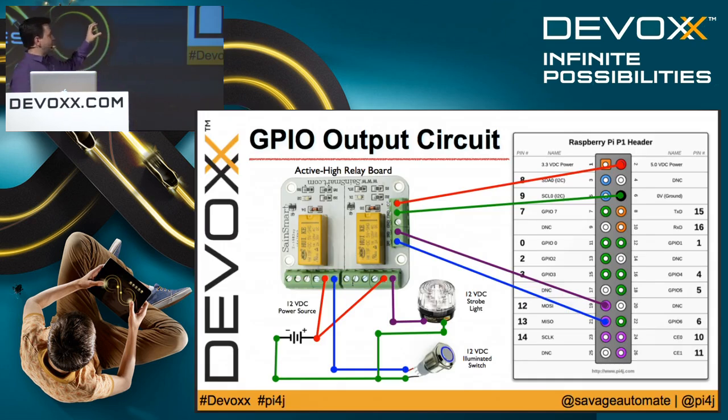So we've got a relay board that we're going to connect to, and we have to provide power to the relay board for its circuitry to run. But then we're going to connect our two GPIO outputs, number 12 and 13 up there, and that's going to connect to input signals of this relay board. So when we signal those output pins high, it's going to trip this relay. And so with this very low voltage, low current, we can signal this relay board to activate one of the relays that's on board. And then we can use a higher voltage circuit on the back side of the relay. So when the relay switches, we'll close the circuit for the higher voltage circuit. And that's how we can control things. That's how we're set up here in our demo board, and we'll run an example here in just a second.